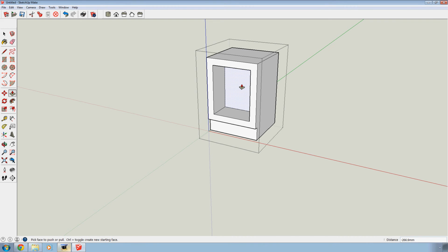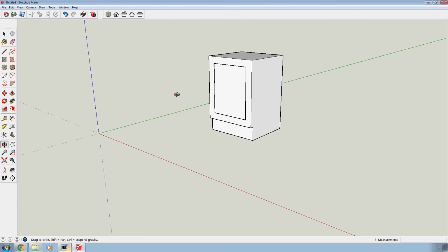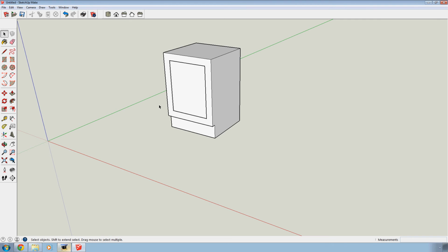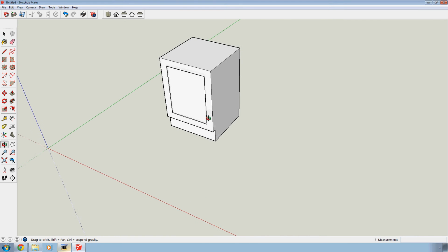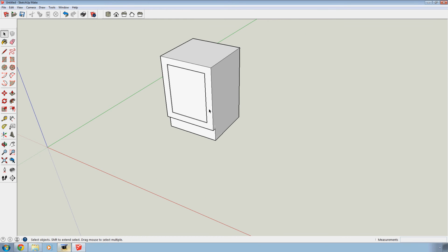That's obviously much too far, but you remember what I was saying earlier about doing exaggerated motions. Entering the actual correct number, in this case is going to be 7, pressing enter, and you see it jumped, and I now know that that is actually on the 7. So there we go. Now we've got our first unit. This is a 600 unit, and we will modify this unit to get the different widths that we will want.